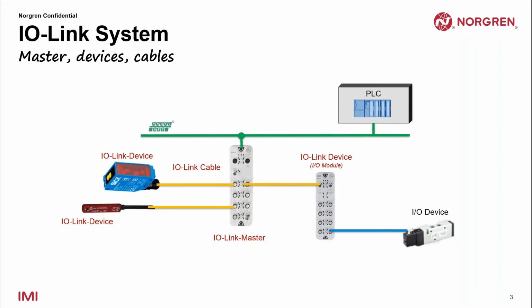So I like to think of the IO-Link masters, again, as a translation device that can transmit information across various networks. IO-Link devices are the products with the integrated intelligent sensors on them. Each device has an IODD file, or IO device description, which describes the device and its capabilities. Based on that IODD file, devices and the IO-Link masters can communicate bidirectionally. It can be performance, life cycle, and diagnostics data that can be read from the device, or it can also mean parameterization or configuration that can be written on the devices via the masters.